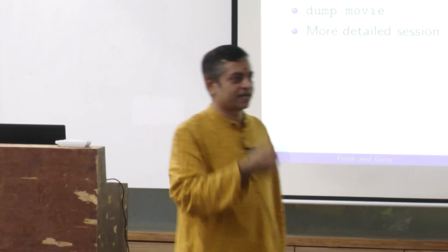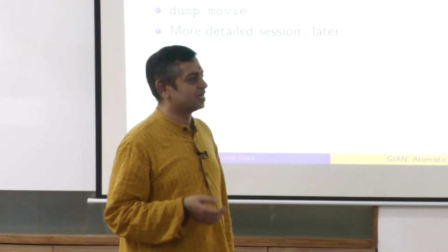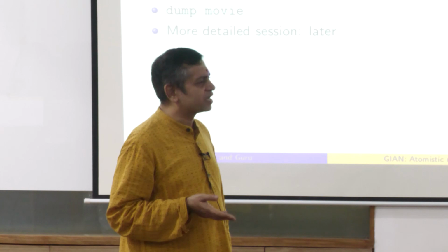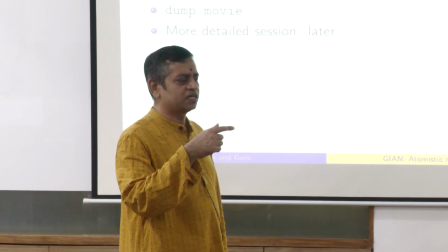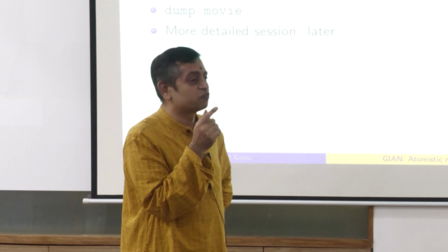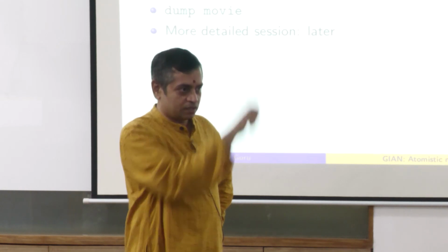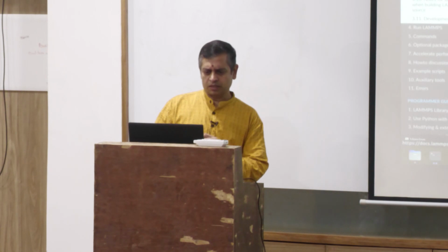This is one of the reasons why I had to redo my installation twice yesterday. Did you use CMake or make? If you had used CMake, you have to remove the header files before you restart. If you go to the LAMMPS manual, they say how to do it with packages with extra include packages in build and packages with extra build options.